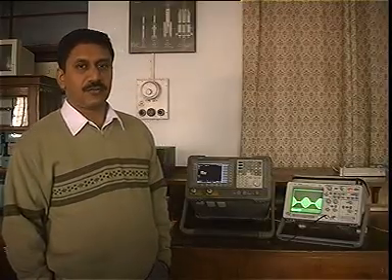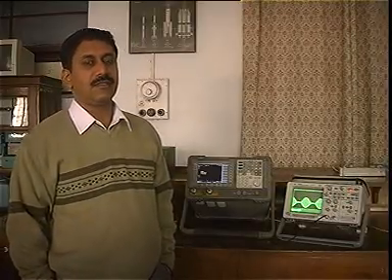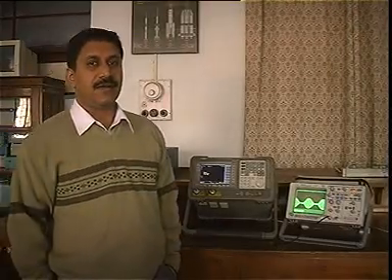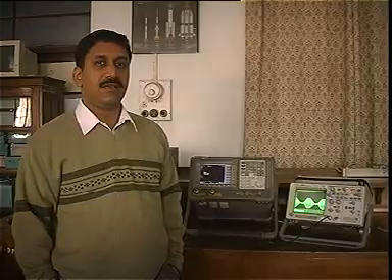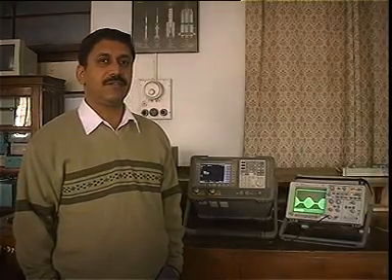If you go back to your textbook, you will see that the upper sideband and lower sideband are located at 502 kHz and 498 kHz. That is fc plus fm and fc minus fm. fc is 500 kHz, fm is 2 kHz. So I will have fc plus fm at 502 kHz and fc minus fm at 498 kHz. So that's where I should expect them.